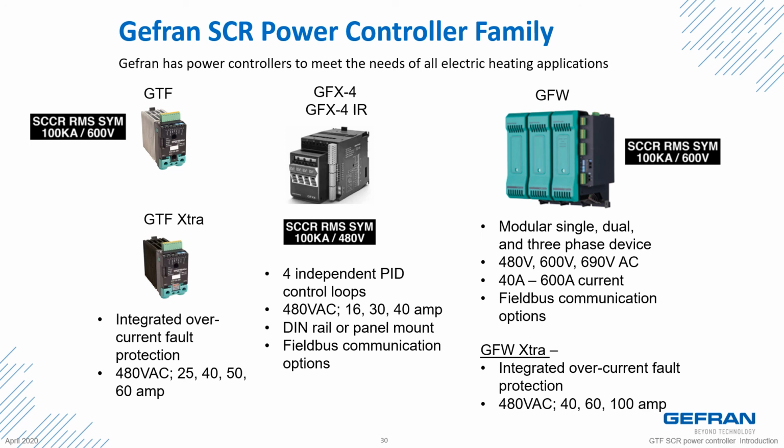The GFW Extra is similar to the GFW. It has an integrated overcurrent fault protection, which replaces the high-speed fuse requirement. It's rated at 480 volts and 40 to 100 amp current.